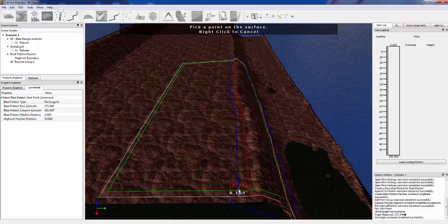And then based on your 10-foot offset and the settings that we had, we'll give you additional snaps so that you can snap to this 10-foot, 5-foot offset. Basically 10 foot from the high wall. So we're drawing you this blue polyline that shows that 10-foot offset. And then we're also showing a green polyline, which is the blast pattern offset. It can be 0 if you don't want any offset at all, but I'm just going to go ahead and select in here.